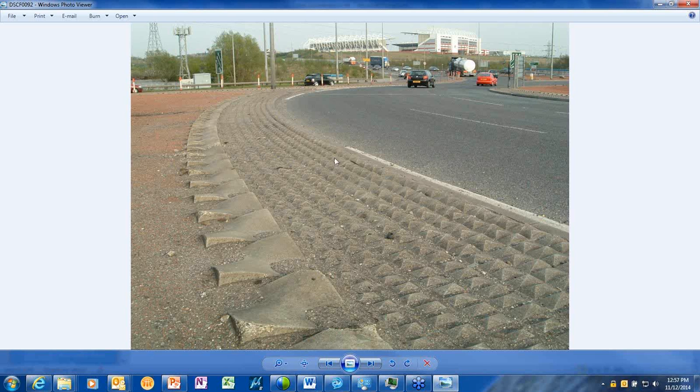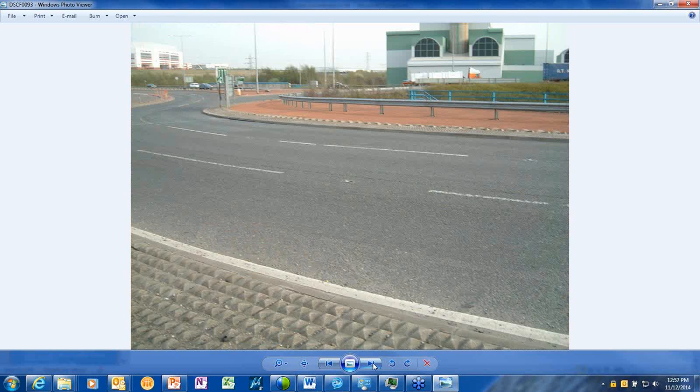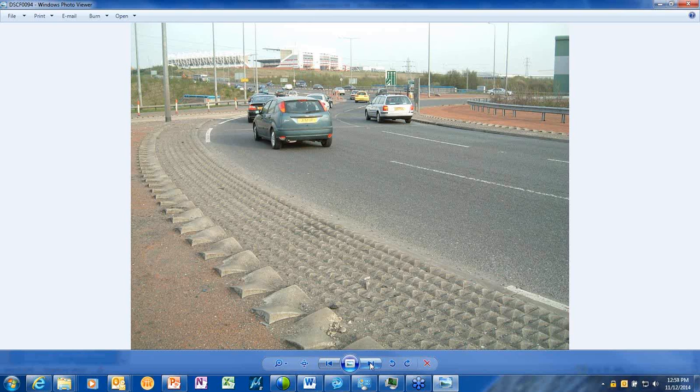So this is going to discourage trucks from overtracking. It's going to discourage pedestrians from walking in these areas where they're restricted. Actually, this roundabout is an interchange roundabout, so there's really no pedestrian crossing accommodations whatsoever. And the whole idea is to keep them away from the roundabout to begin with. And of course, it's left-hand drive too.